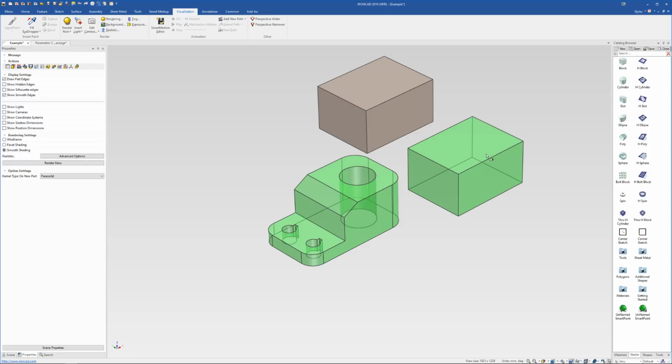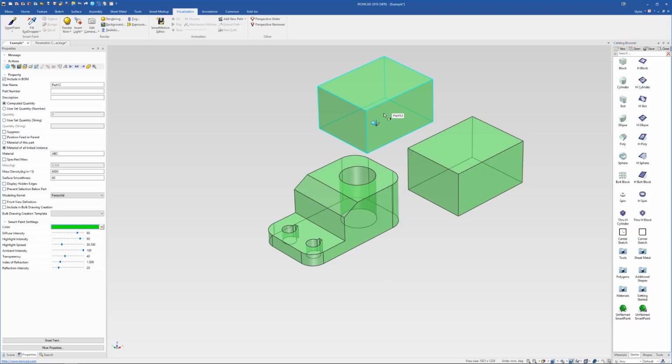Obviously, in the one model, you might have multiple parts with different materials that are the same color. So sometimes you want to just copy the color, not the material. This type of one here will also copy the material properties. So if we select down onto this one, it's now got our ABC material at a 6,000 mass density.